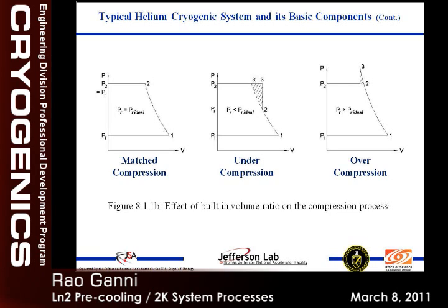So what happens is, unless the suction pressure and discharge pressure match your suction condition and discharge condition. The suction condition is normally matched. The discharge condition, you can have two different things. One is, you may be compressing here and you open your exhaust valve, and the rest of the compression has to happen in your discharge pipe because the screw hasn't compressed all the way. Or you might not have opened your outlet port yet, and the compression might have gone over. So your over compression is real.